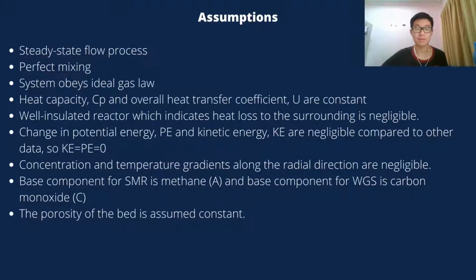Before developing the mathematical model, assumptions were made. First, this is a steady state flow process. Second, the system is in perfect mixing. Third, the system obeys the ideal gas law. Fourth, heat capacity and overall heat transfer coefficient are constant.